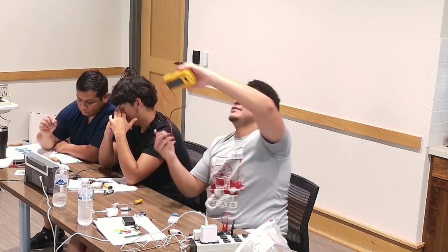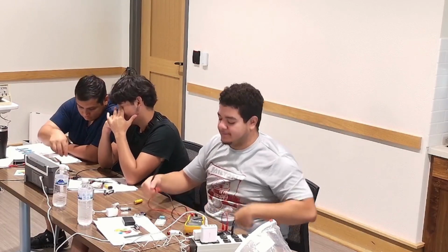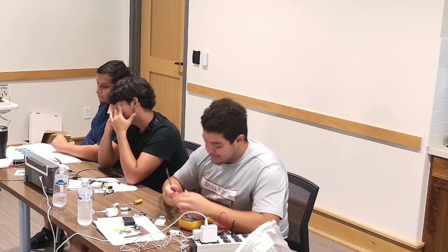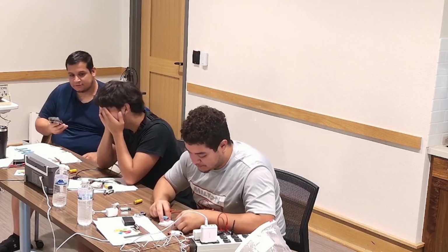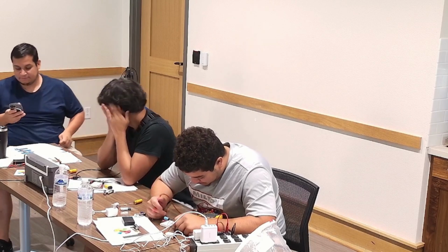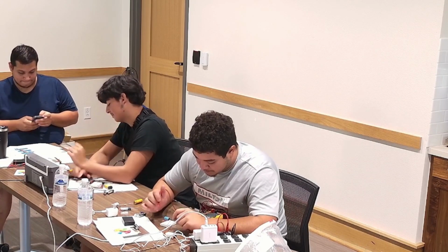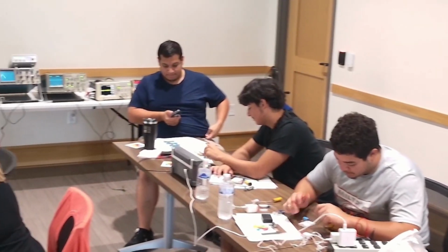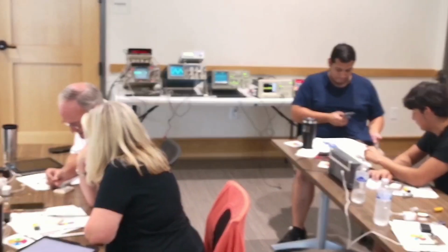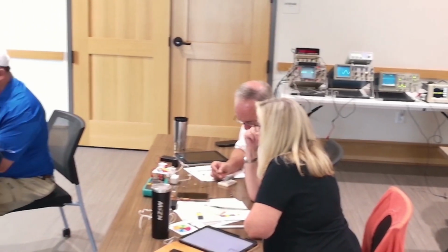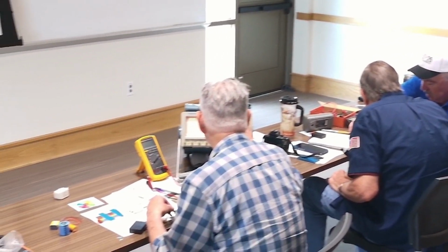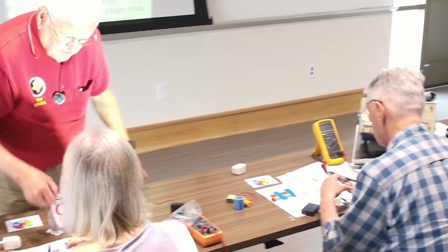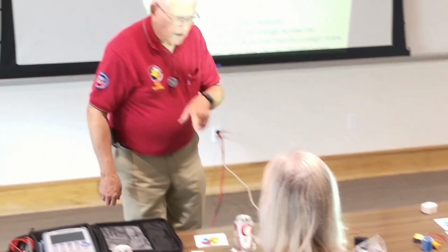It's going the wrong way. No, it's fine. We just change the leads. This meter will automatically tell you if you have negative, negative, or positive, positive. Okay, so we take this off. We're starting to discharge, but if I whip this around here real fast and do that, it'll go down much, much faster. That's the idea, and it's still disconnected. And why would we do that? We're fixing to talk about that.